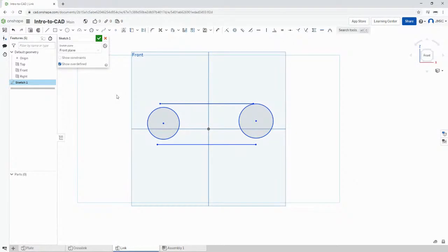Next, let's add a tangent constraint to reiterate our tangent tool. So once more, selecting tangent constraint, selecting this horizontal line and this circle, and I'm going to hit escape, and I want to show our absolute beginners watching right now the effect of having a tangent constraint.